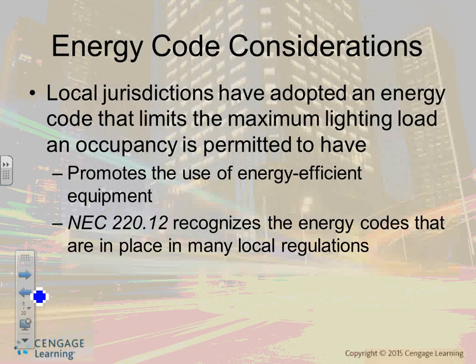So if they're planning to add another 10% to the building, what do you do? You take your load and up it 10% for future expansion. At the end, when you do the calculation, you come up with the size of a panel, 600 amp. Multiply by 1.10 and size your service. That's how we typically do the whole thing. Because you're going to up the whole thing 10%, that will get you an addition for the future. If that makes sense. Yes, sir.